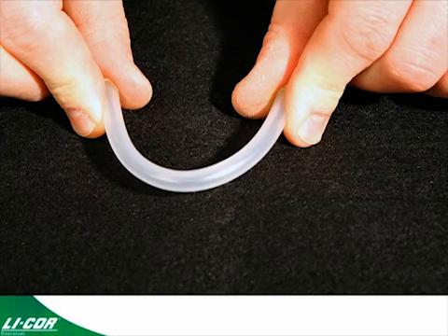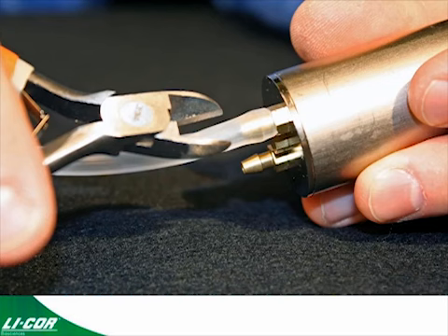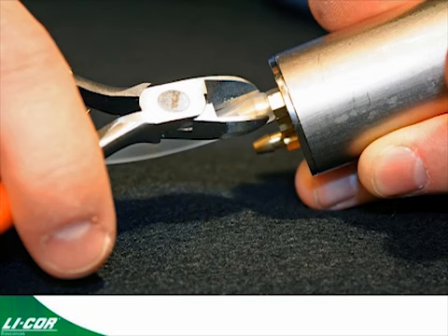If you overbend the tubes, as demonstrated here, this will result in a crease, and that crease causes a diffusional leak through the wall of the tubing. A technique that we've developed here at LI-COR to remove the tubing from hose barbs is to use a pair of side cut pliers and grasp the tubing at an oblique angle to the barb.